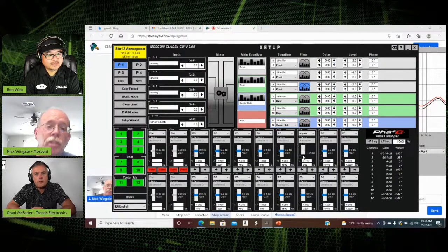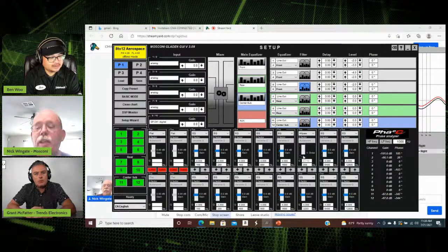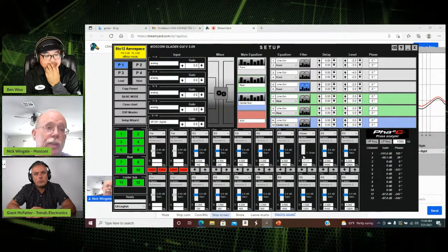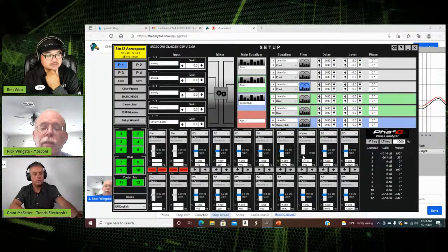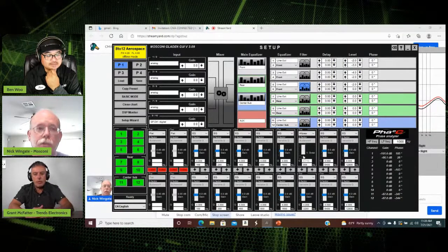This is my experience, to be honest: I've heard these terms and I have never heard explained what those orders mean. Basically, it's the degrees of phasing that you're working on, that you are affecting. For lower frequencies, you want a faster roll off. For higher frequencies, it's less of a roll off, quote unquote. That's about as simple as I can explain it. I don't want to go into the math because it is math deep. Like I said, if you want to learn more about it, go take a look online.